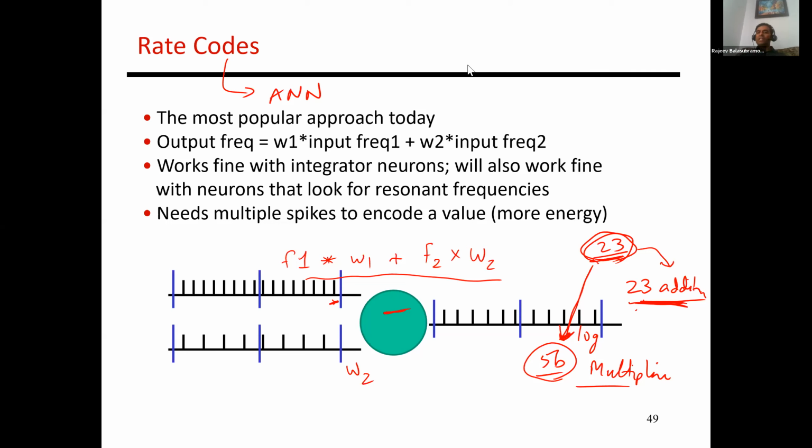So we're essentially saying that there are two things to consider, right? So firstly, are you creating something that has more power algorithmically? And the second thing is, are you creating something that's more efficient in terms of hardware, right? And so this proposal of taking rate coding and attaching a value with every spike, I think that's certainly more energy efficient, right? Because it prevents me from doing these 23 separate additions. But algorithmically, it's going to have the same power as rate coding. And in terms of hardware efficiency, I would argue that this is sounding a lot like an artificial neural network itself.